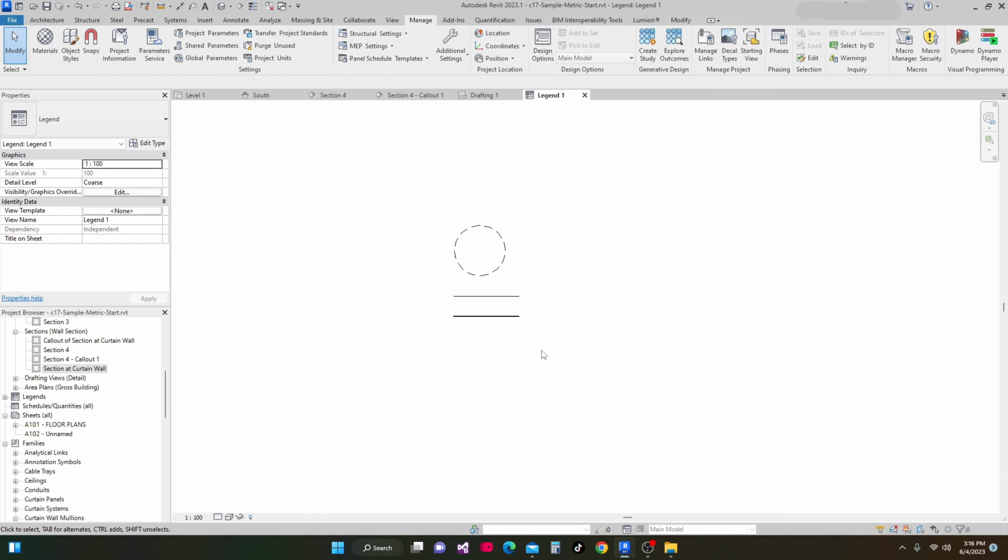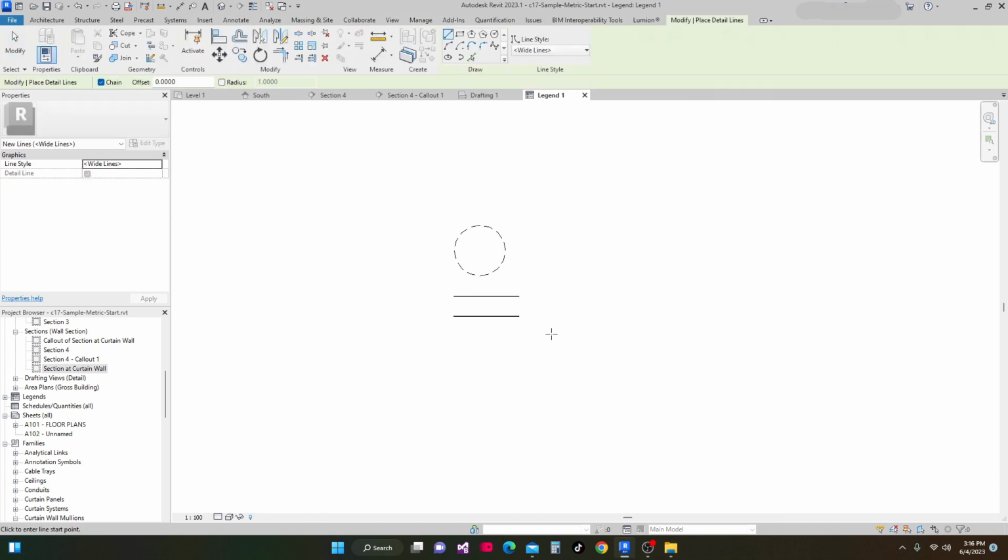And then I'll go back to that DL, and if I go to this line style, I click this down arrow, and you have seen this red, and I click this, and then I make a line, and here is my red line. You can create any line style as you want, just as what we are doing in our AutoCAD. You can also make your own plot style.